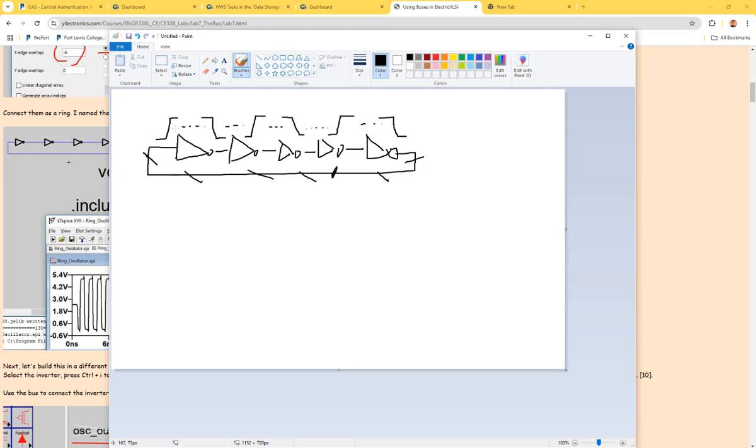So whenever this one goes from 0 to 1, after it goes through all the gates, it pulls it down to ground. It's still the same wire, but it's forming a pulse like this, even though it's still the same wire, because of the time delay. If there's no time delay, it won't be possible. A wire will have the same voltage, right? Does that make sense? It's still the same wire, but at different times. Keep in mind, this is time. So at different times, the same wire will have a little pulse being formed.